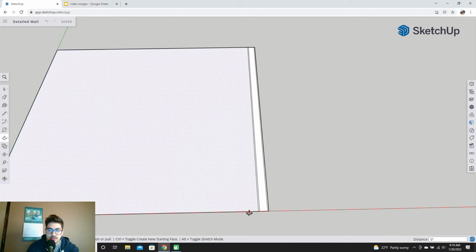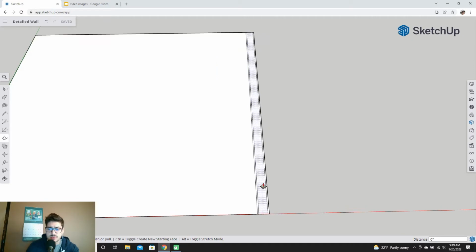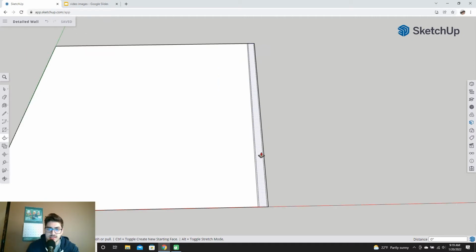But right, because it's going to be 3.5 inches, well, it's actually 4.5 inches once you add the drywall in all directions. So you would actually want it to be 10 feet plus 4.5 inches on either side. I might do that in a future video. This one's going to be long enough as is.